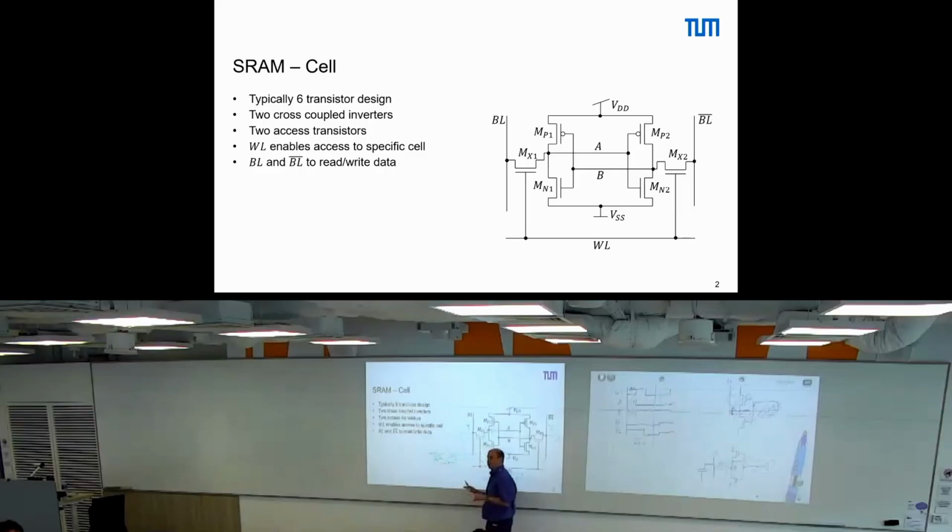In practice, it looks very similar to what you have for the SRAM cell, but with different transistor sizing. So it's a much stronger driver. What you see then is that this sense amplifier effectively sees a small voltage drop here. I'll take another color. A small voltage drop here in the bit line and bit line bar, compares this and amplifies it up to the full level. So I write here sense amplifier.